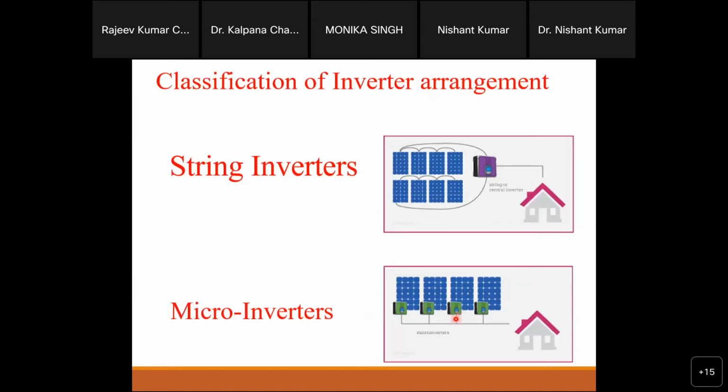But yes, on the demerit side, the losses are a little bit more, and the auxiliary power supply, converter protection circuits and all those controls will be required here. So this is a little bit costly, you can say in one word. But on algorithm complexity, both are more or less the same, because the same converter control will apply for one converter or for multiple converters. The control complexity is the same, no issue. But the supporting devices will be the costly part here.